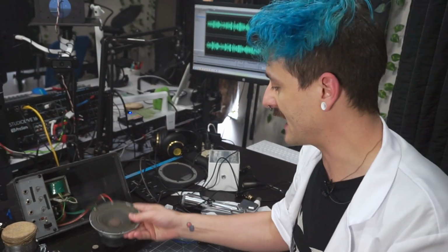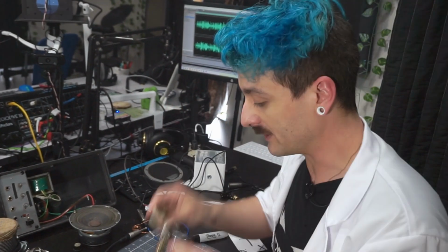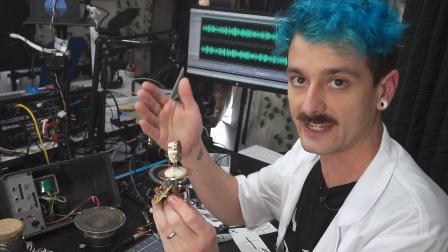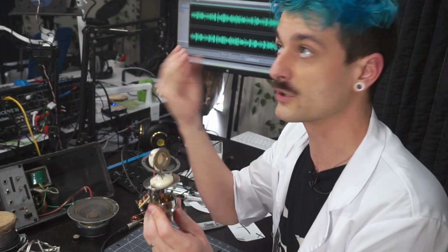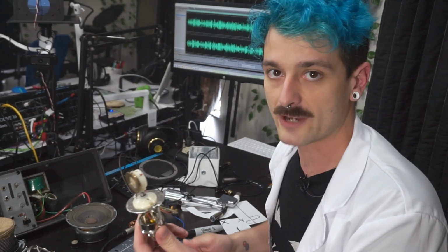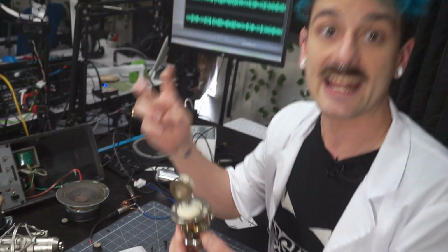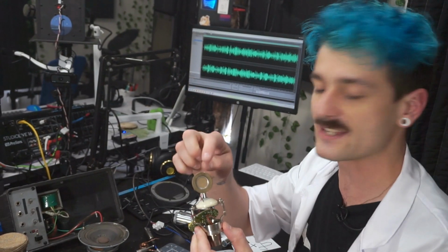With a speaker, with a dynamic microphone, you have to be moving that diaphragm back and forth with your sound wave. Your wave has to do more work. With this, my sound wave just kind of touches it, and we're measuring such an infinitesimally small amount of movement, you can get a much more precise signal and pick up higher frequencies more easily. That's why capacitor microphones, what am I, from the 1940s? That's why condenser microphones are so sensitive. Every little sound wave has to do less work to be heard.